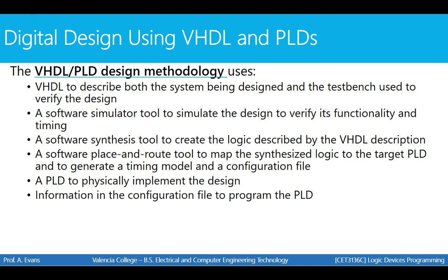So when we talk about VHDL, there is a design methodology that is used to create the code you're going to run on your PLD. VHDL is used to describe both the system being designed and the test bench used to verify the design. So the test bench is a secondary piece of code that's going to verify that your first piece of code works the way it should. We're going to learn how to write both a VHDL design as well as a complementary test bench during the course of this semester.